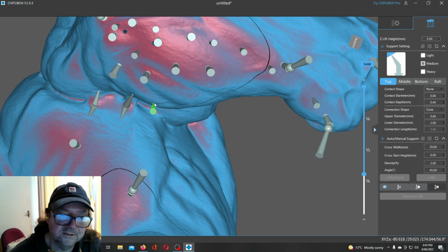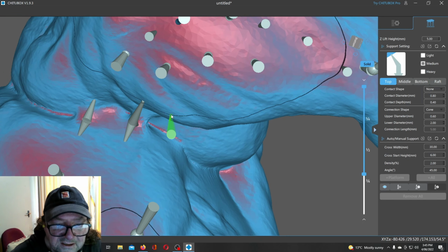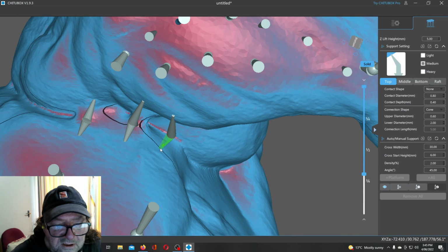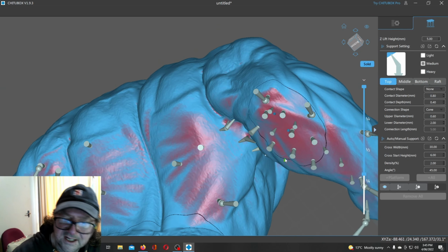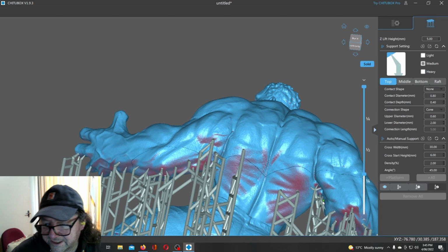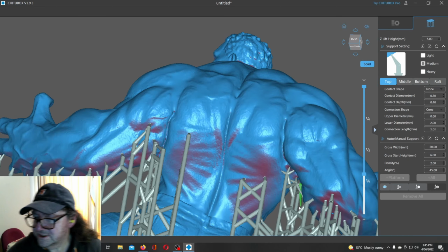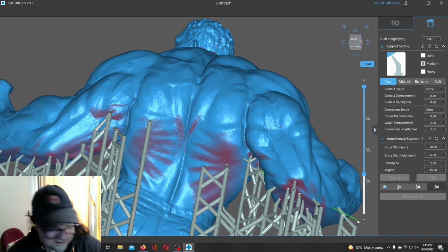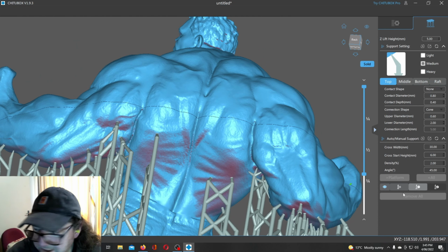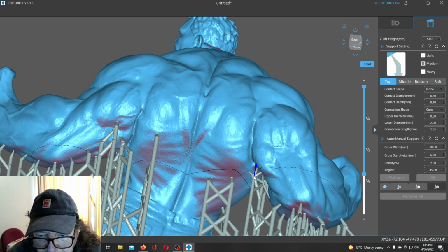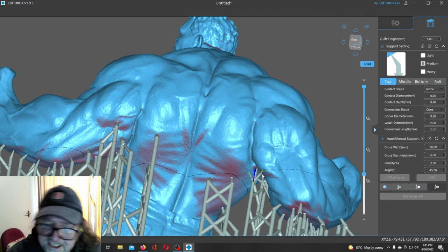Double click, and we've got, what are you doing? Oh, that's a bit hidden. Hang on. That wall and that wall. I'm going to have to look at this. I might have a funny angle on these. Yes, I do. Okay, I'll show you what to do there. Because supports don't like to build downwards like that, you've got to just shift the pivot point. Let's just go escape. So I'm still in modify over here. I just pick up the ball, drop it down so that they're all sloping downwards.